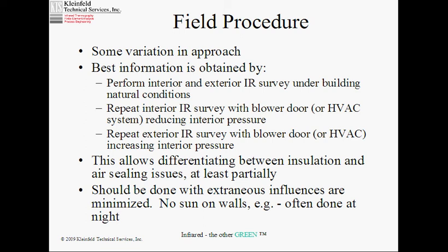The best information is obtained by going to the building under as-is conditions, preferably at night when the sun is not in effect, because if you've got sun shining on the outside of a wall, that outside surface gets hot, and potentially, even though it's cold outside, you've got heat flowing into the building, net flow, and you see all the nice warm areas on the inside. Well, if you see warm areas on the inside when the heat's flowing in, in fact you've got a problem, and you're going to interpret it as, oh, that's the area that's good. So you do need to be aware of when it's done and what the surrounding conditions are.